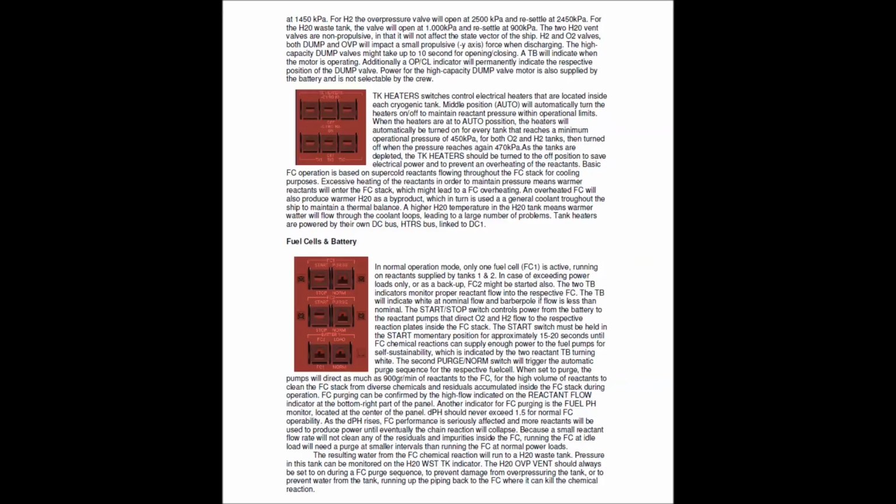The two H2O vent valves are non-propulsive in that it will not affect the state vector of your ship. H2 and O2 valves, both dump and OVP, will impart a small propulsive negative y-axis force when discharging. The high-capacity dump valves might take up to 10 seconds for opening and closing.